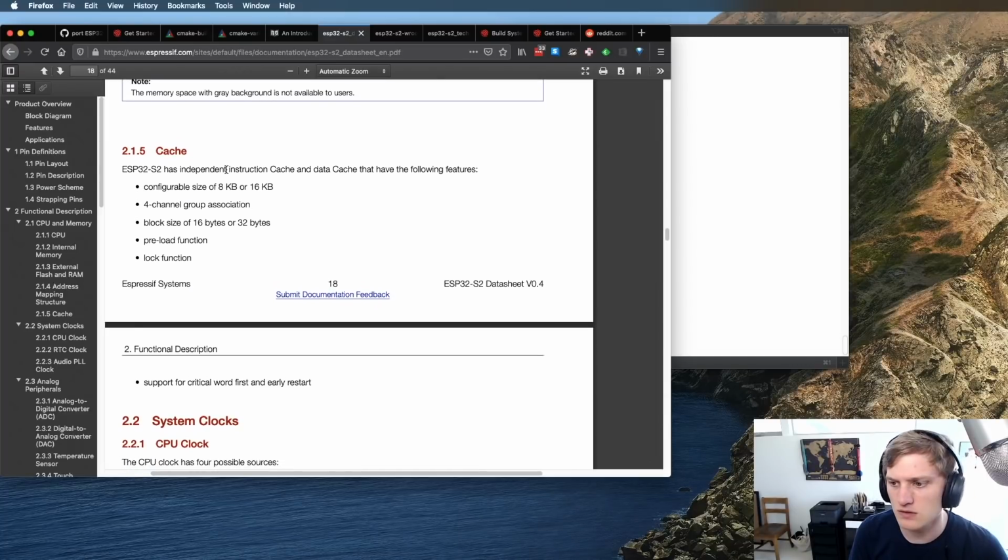It's also interesting. For those of you who haven't taken CPU design courses, there's kind of two common architectures to CPUs. It's only been over a decade since I studied this, but it's von Neumann and Harvard architecture. One of the things that distinguishes those two is how many memory buses you have coming out of the CPU. Harvard architecture, if I remember right, has at least two memory buses, one for instructions, which is your assembly code loader, and one for data, which is like read me a value and put it in a register sorts of operations. And outside of that, you get separate caches: an instruction cache and a data cache. And it tells you how it computes that and figures stuff out.